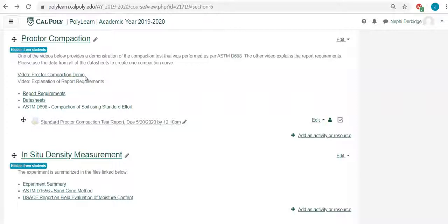It's a very common test, and it's used for grading control. When I say grading, I'm talking about preparing a site for a building that's going to be placed on that site. So preparing the ground, that's grading. So it could be changing the contours, changing the elevation by adding earth or cutting away earth or densifying the earth that's there. And that's what this test has to do with, is densification.